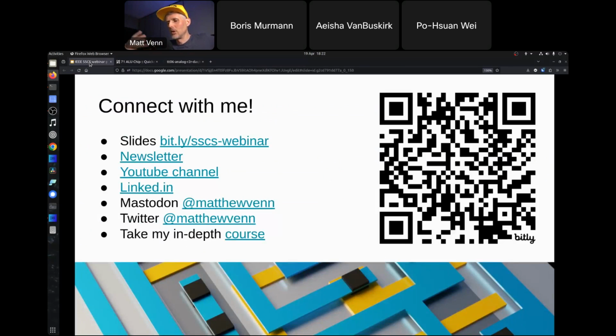You can then use Magic to generate all the P cells, so all your cells match, or you can create them yourself. I like to use the automatic version. If you're using KLayout, then you can import all those standard cells. If you're using Magic, they're already there for you. And then you've got to do the wiring. Then you've got to do post layout simulation, and LVS. And it's all much more laborious and kind of manual.